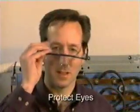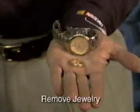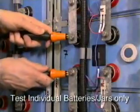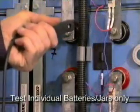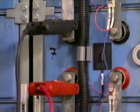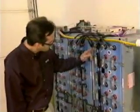Before conducting any tests, it's important to take safety precautions required by the facility or your organization. Be sure to protect your eyes. Remove all jewelry, including wristwatches. Also, never forget that analyzers are not designed to test entire strings at once. Test individual batteries or jars only. We begin with a visual inspection.